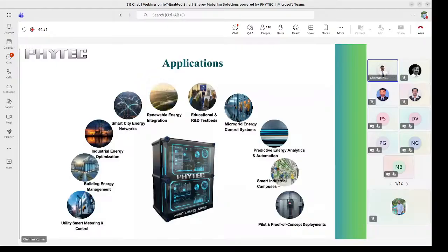First, the client sends the AARQ request. The client is whoever wants to get the data from the meter. The meter then responds to that AARQ request with an AARE response. Then if the client wants to read some OBIS code, it sends the get command, and the meter responds with the data specific to that OBIS code.